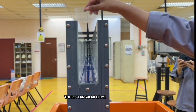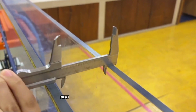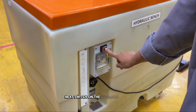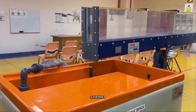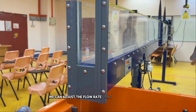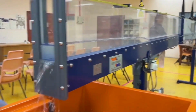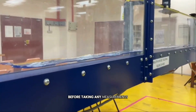The rectangular flume was mounted securely onto the hydraulic bench. Next, we need to measure the flume width. Next, switch on the hydraulic bench to allow the water to flow through the rectangular channel. We can adjust the flow rate using the control valve until a clear hydraulic jump is formed in the channel. We wait until the water flow becomes stable before taking any measurements.